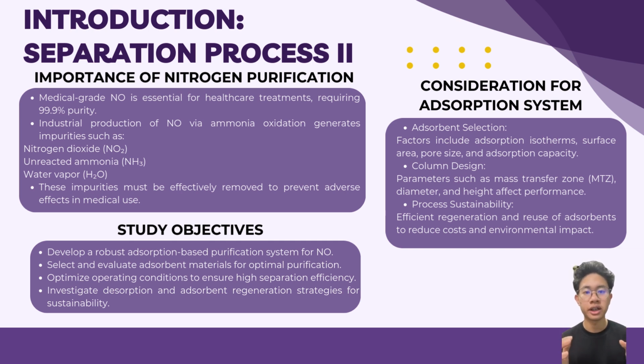Medical-grade nitric oxide is crucial for healthcare, requiring a purity of 99.9%. However, industrial production introduces impurities such as nitrogen dioxide, ammonia, and water, which must be removed for safe medical use. This study aims to develop an adsorption purification system by selecting the best adsorbent materials, optimizing the reacting conditions, and also investigating the desorption and regeneration for sustainability.